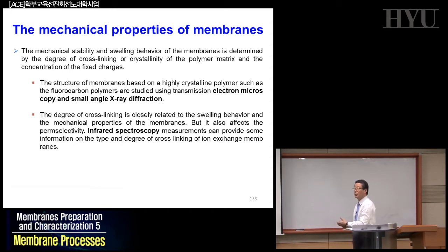Usually, mechanical stability is coming from the crystallinity and orientations. So when you have a crystalline material, such as ceramic and metals, you have a pretty high rigidity and high modulus and tensile strength, whereas the elongation is a different story. Okay? Elongation is measure of the flexibility of your materials, and the flexibility, of course, is very important as well too.